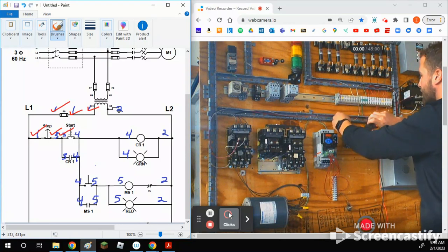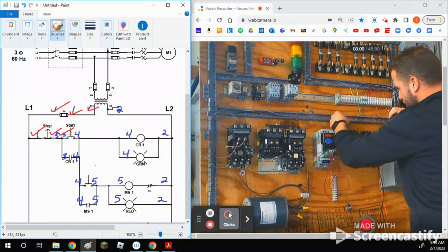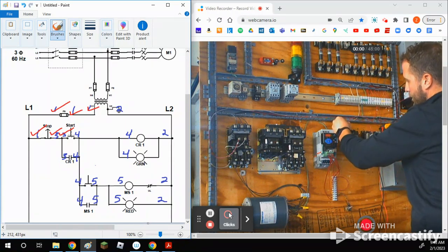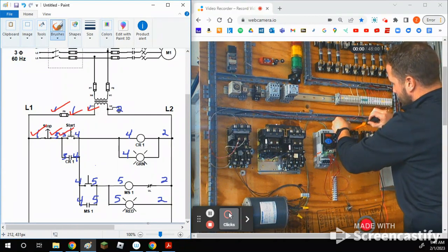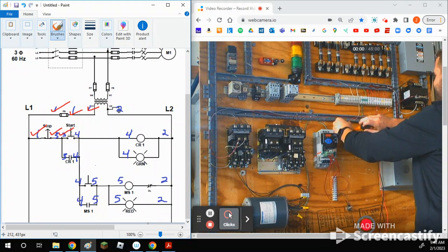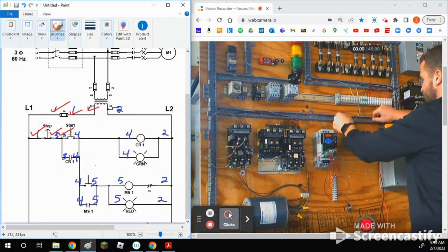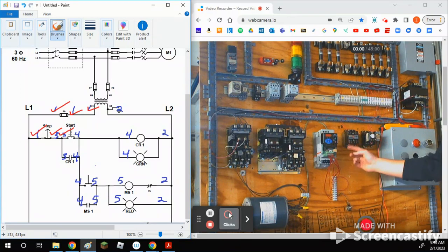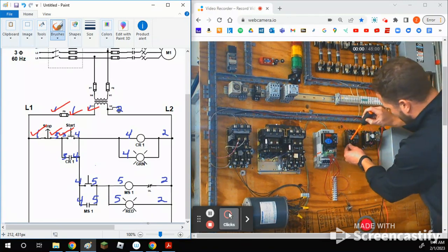Do this so you can see it. Does it matter if I put this thing in the top or the bottom? Want it in the top. Why? It's closer. It's closer. That's a good answer. Because she said so. Remember we talked about line side versus load side? You typically want something coming in to the top and going out the bottom, but it does not matter. If it makes more sense for you to come into the bottom set, it doesn't matter. Okay?